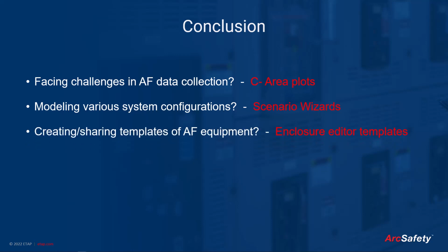Creating, sharing templates for arc flash equipment. Can I do that? Yes, you can. You don't need to have an arc flash library, but you can use your enclosure editor and create templates for same equipment such as switchgears, MCC, and panel boards, and share it across different users. Are you finding it hard to analyze the worst case incident energy? As I demonstrated, you can use the arc flash analyzer for multiple reports, evaluate the worst case incident energy, and then send it to the data blocks, so that the one-line diagram can have the worst case incident energy shown on the display, and that could be printed as a drawing with the arc flash results.